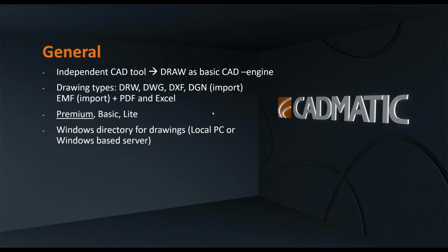Then we have the Basic application level, which means that it actually has a database inside the drawing. So you are able to build your own project per one drawing, meaning that, for example, for some distribution board, you will get all the functionalities for that. Maybe you do a schema or multi-line drawing of that. All the devices inside that one drawing are listed on the project. But still, the drawings are not talking to each other. Let's say they are independent drawings and independent projects in that sense.